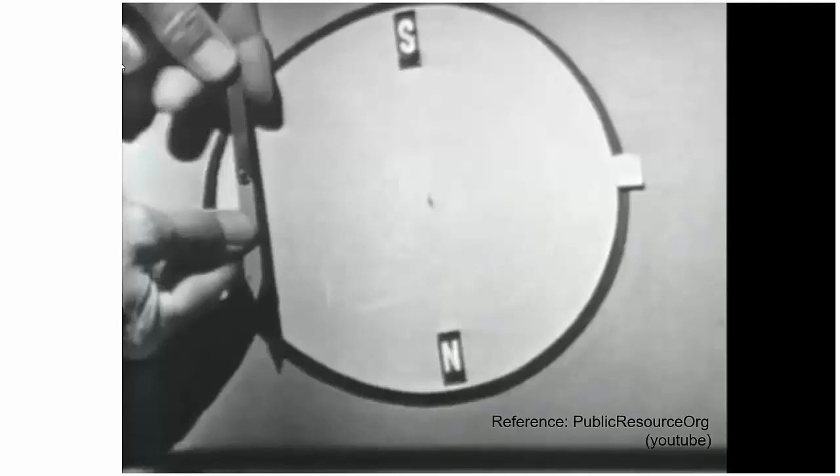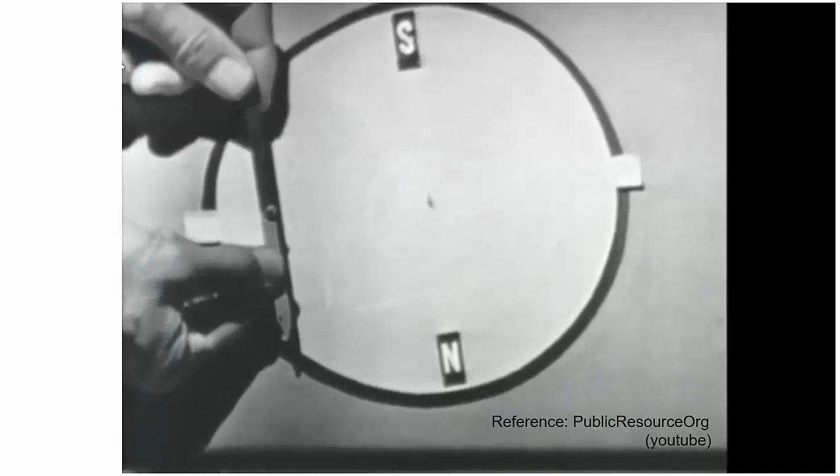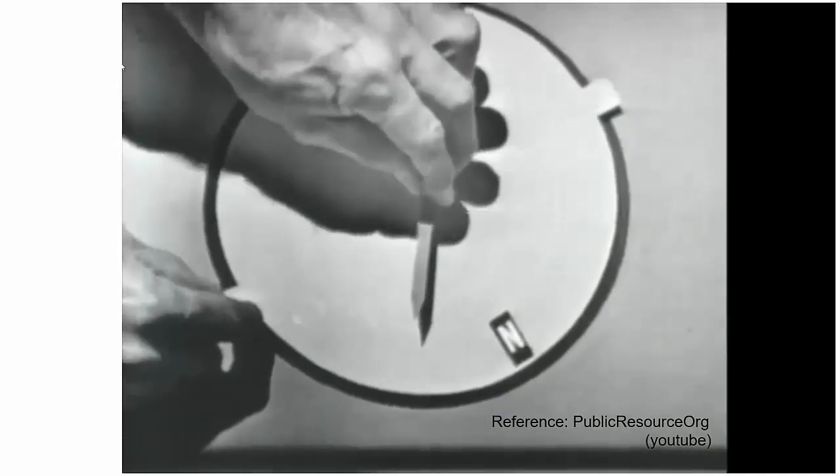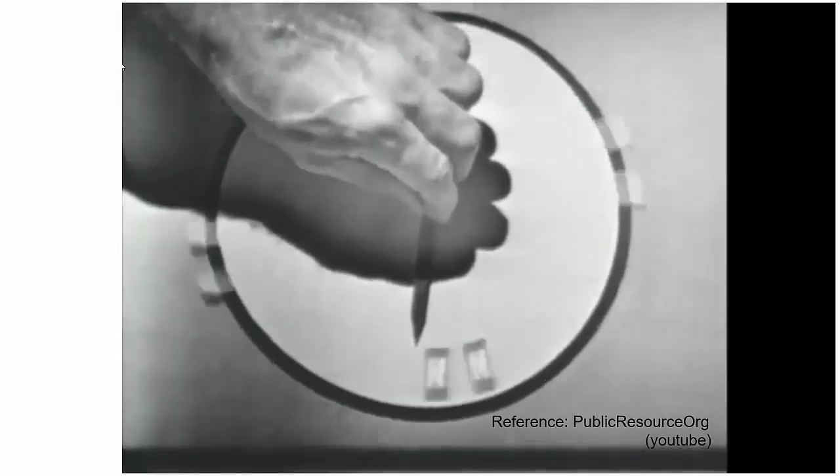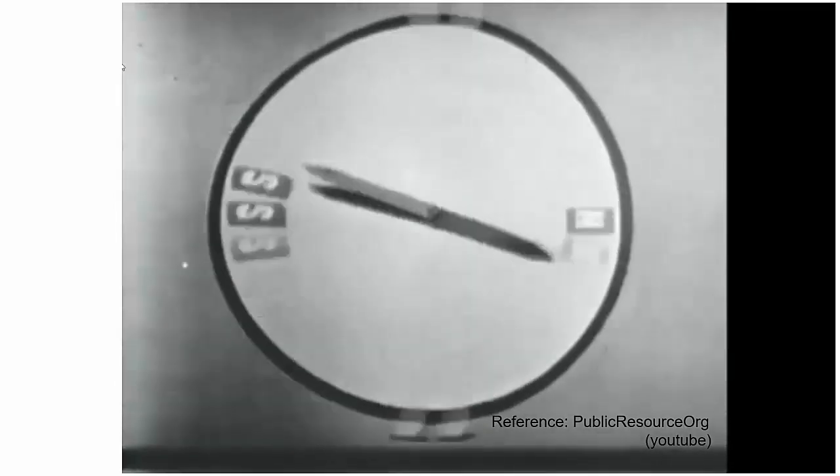Now shown over here is a demonstration to understand how the rotor actually works under the influence of a rotating magnetic field. Note that I just told you that unipolar poles do not exist, so the figure does not show a unipolar magnet, but in fact it must have two poles. Once the needle is placed, it experiences the torque in the direction of the rotating magnetic field, and thus starts rotating in the same direction, with the same speed as that of the rotating magnetic field.